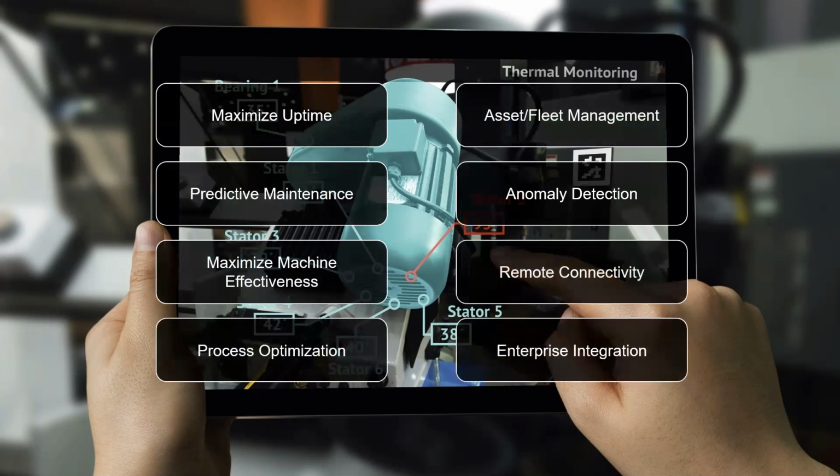It's about 10 simple cases of how things are being used. One is, of course, maximizing uptime, and you achieve that through a variety of ways, including predictive maintenance. Predictive maintenance is simply saying, oh, this machine has been running hot. I've been capturing thermal data from it for the last 6 months. Something's going on with this part, or this motor is drawing more current. I can watch that graph start to spike. Maybe I've got a bad bearing. Maybe there's additional friction. Instead of having an unplanned outage, I'm going to wait to third shift where we're not running the machine, and I'm going to change it then on my time instead of when the machine suddenly craps out a week from now in the middle of the busiest part of the day.